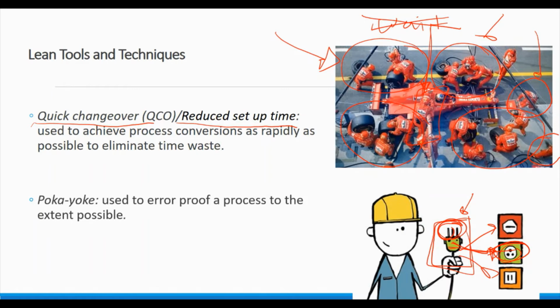That's a way of poka-yoke. You try to put the hose into the car, it will not fit, because only cars that use diesel can pump diesel into the car. That's another way to make sure we prevent any kind of human errors, kind of like baby-proofing the process to make sure it only happens one way.